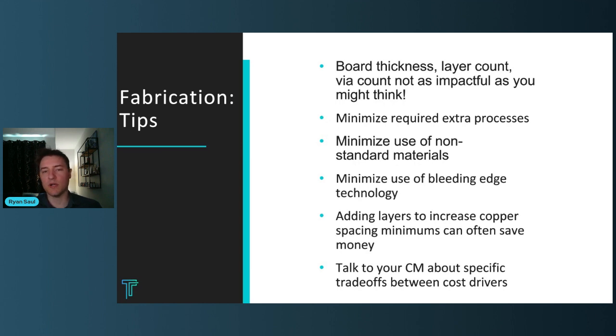Like, who wouldn't want to design a board that couldn't have been built 5 years ago? But when you're pushing the limits of what can be done, you are dramatically constraining the fabricators that could ever do your job. And even for those fabricators that technically have the capability to do your work, they are going to charge you more just to use those emerging technologies that I'm referring to. We see this most commonly with copper spacing and incredibly thin dielectric layers.